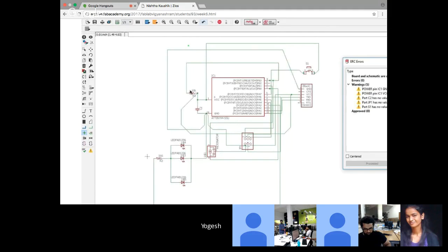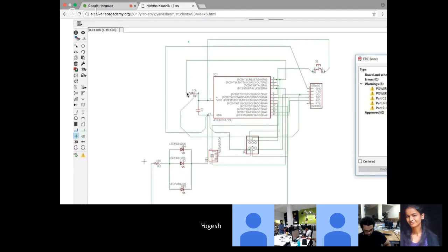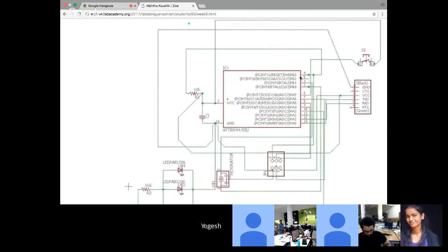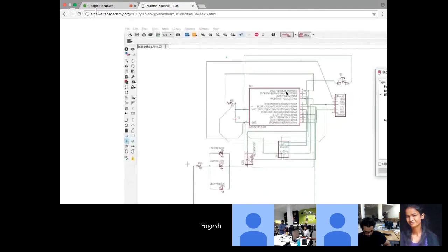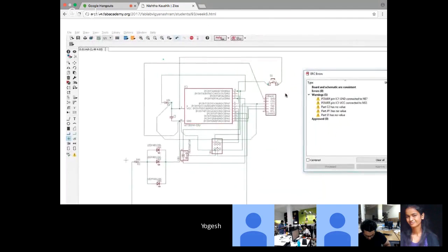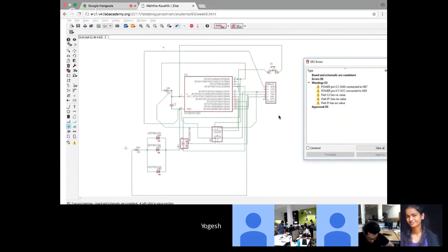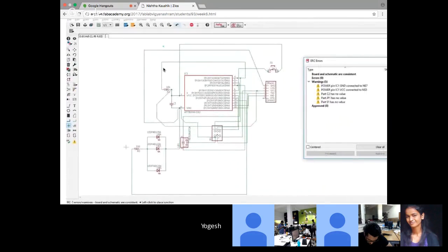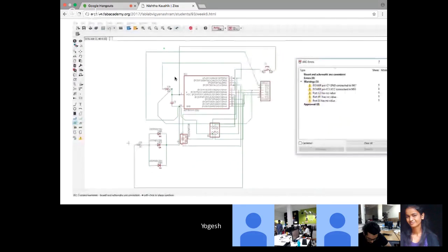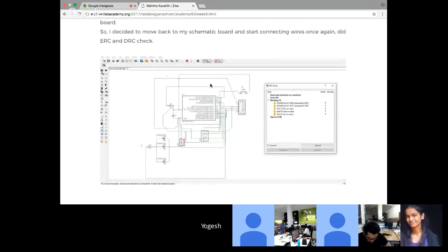You have to see that this wire is highlighted and the other part of the resistor or the other part of the IC is getting highlighted or not. So this is the thing that you can use to check if the connection is there or not. Also, it will indicate every instance of the wire available on this schematic. Consider that you have multiple grounds. If you click on a ground, it will highlight every other ground present on the same schematic. So this is the trick that you can use. Keep trying that command.